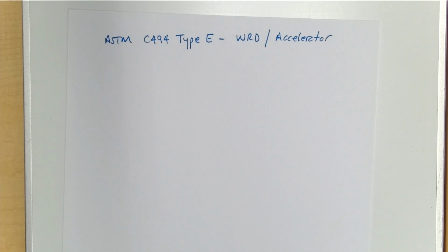You have to be careful about something called admixture compatibility. Because if you put in a retarder and a type S stabilizer and a type S VMA and what else do I want in there? An air entraining agent and a pozzolan, maybe two pozzolans, and a cement, it is possible to randomly find a formula that nobody else, because they don't check all these things, right? You're the manufacturer. Put them together and the concrete won't set. Or worse, it'll set so fast you can't do anything about it. So admixture compatibility is a big deal.